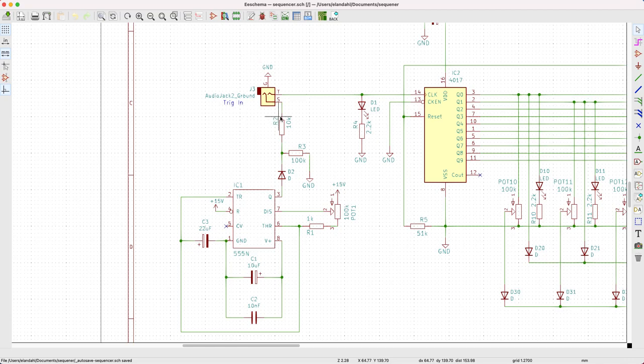Or alternatively, and sort of by default, I guess I should say, the clock input will actually come from a 555 timer operating in astable oscillation mode. So by now we're very familiar with this sort of circuit. There is a power supply that goes through a pot. That was the pot on the right-hand side. And that will affect the RC time constant of this line, which here's the capacitor, 22 microfarads electrolytic capacitor, and